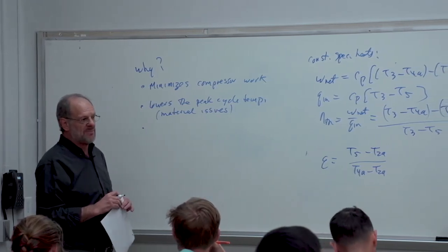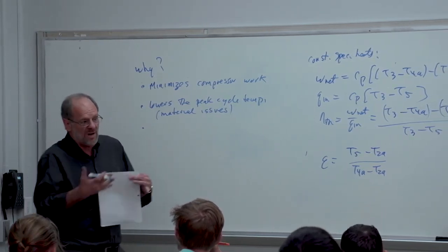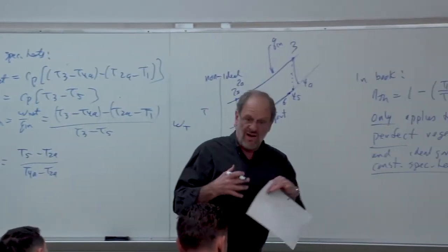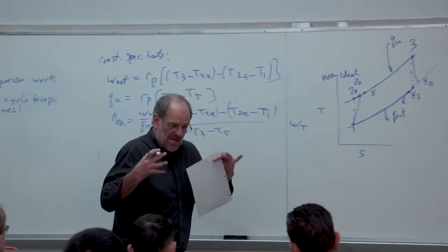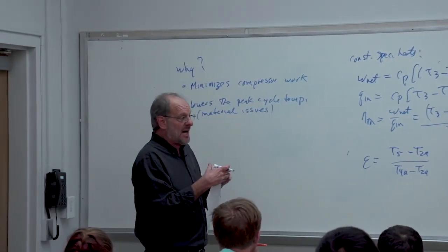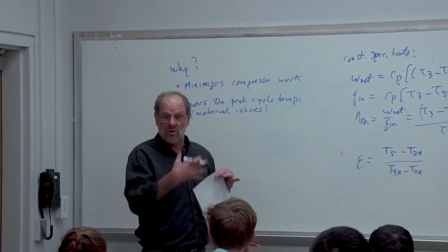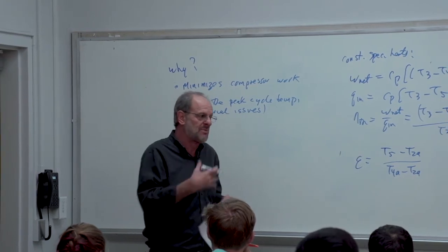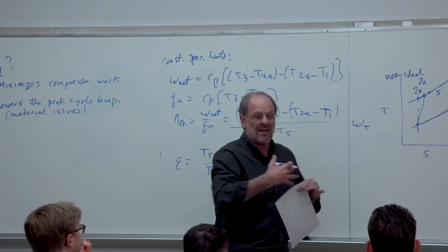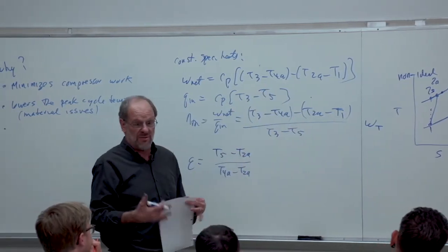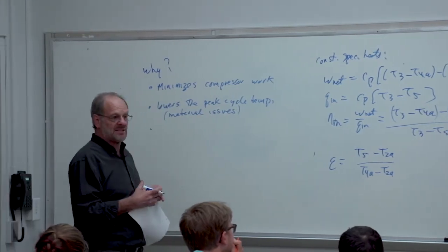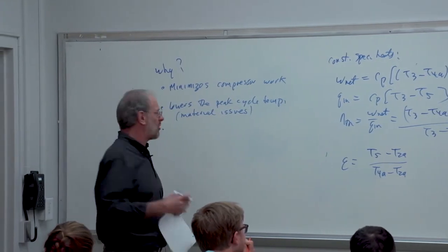And then another thing we might note is that as we're able to lower the temperatures in the cycle, doesn't that also increase the density? Right? Higher temperatures mean lower densities, lower temperatures mean higher densities. If we have higher density, then that means we can get more mass into an engine of a particular size, and therefore develop more power from that engine of a particular size. I mean, after all, the power is not just a function of the net work per unit mass, it's also a function of the mass, right? Lower densities mean less mass, higher densities mean more mass, and therefore more power.